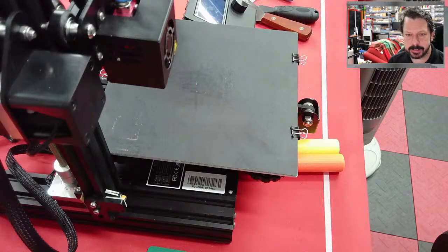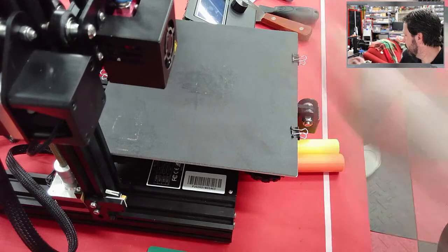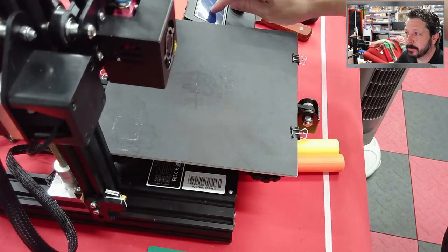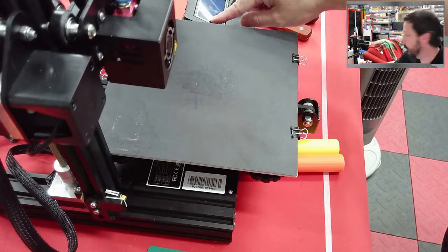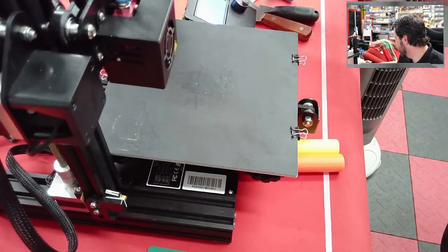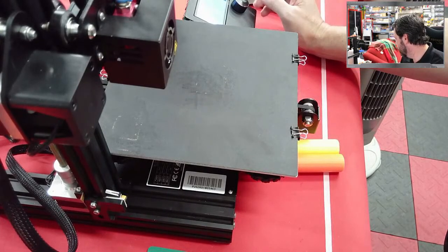The E-steps I didn't get a lot of comments about. That's the one thing, other than leveling the bed, that's probably the easiest to do. I may not have shown it the easiest way, because I did go through the terminal, but for most printers, you can change it directly on your control panel. And in this one, I don't have the printer on, so I've got to boot it up. But in this one, if you go to